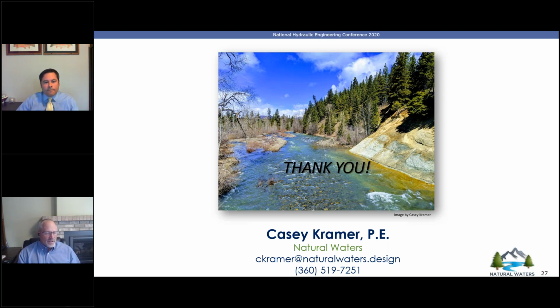Well, if I understood that all correctly, one thing that's pretty helpful is that you can export your cross sections from the 1D effective model and import those directly into SMS and compare your 2D results along those exact cross sections. So that can be helpful. But as far as criteria regarding the FEMA, again, we'll have to look to the specific guidance there. There's plenty of tools available. It really comes down to what they require in the guidance.